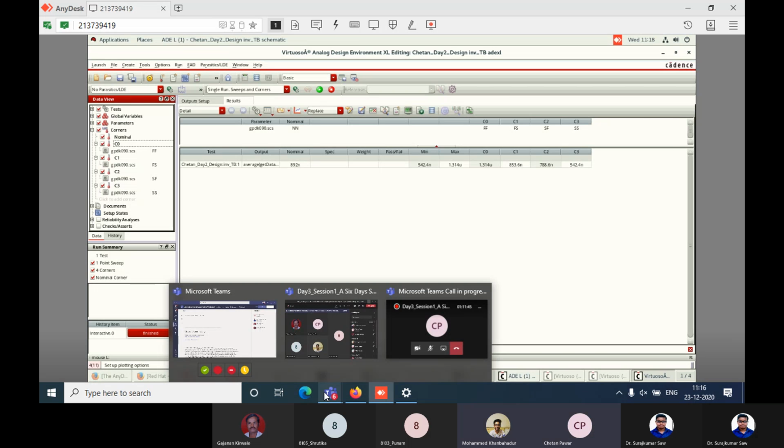Yes, good. Yes, sir. Now, maximize this screen. Maximize this waveform screen, Poonam. Now click on that out net. Good. First click, one time, then right click there. There only you should right click. Send to calculator.